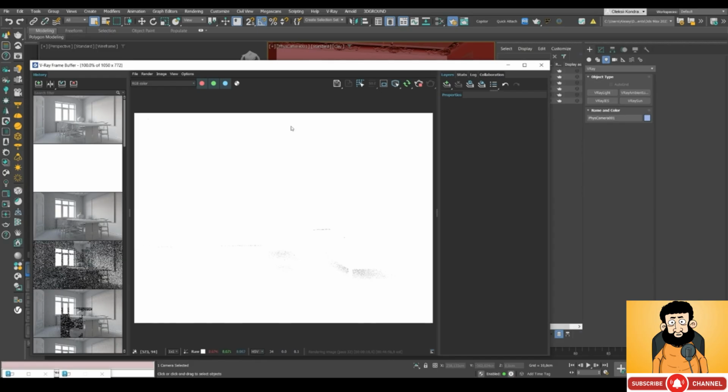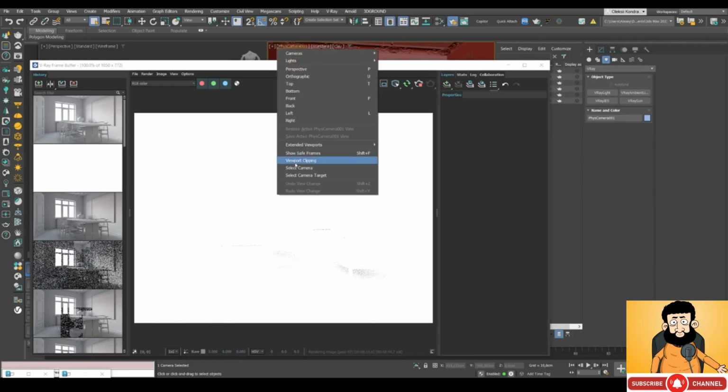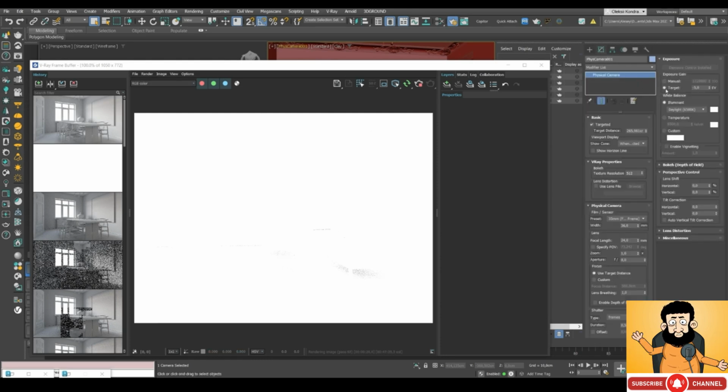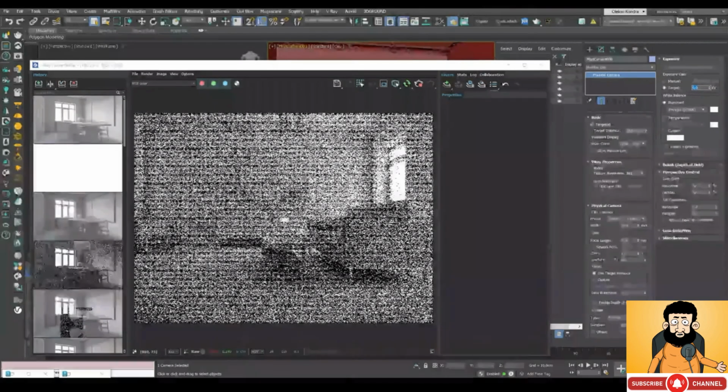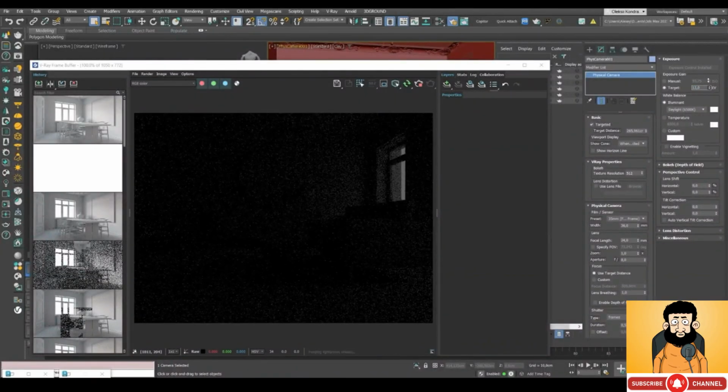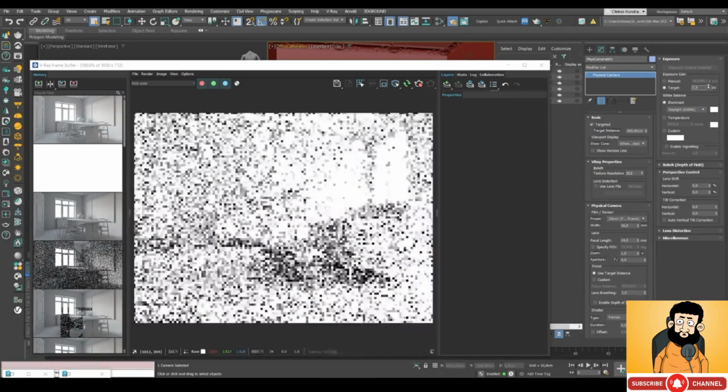It's overexposed, which means that we need to adjust our camera. So we click select camera, and each camera, except for the most standard one, has an exposure setting. Target EV stands at -5, and we'll bring that to 0. See, the brightness has gone down. Let's increase it to 5 though.